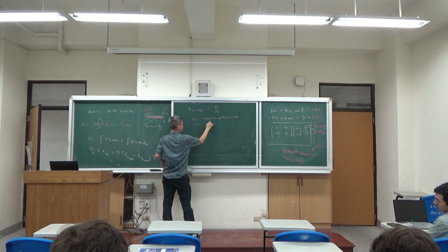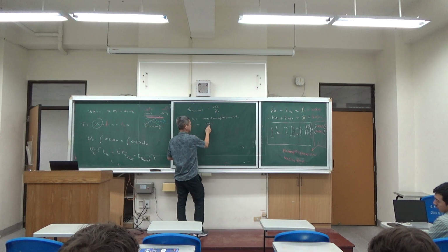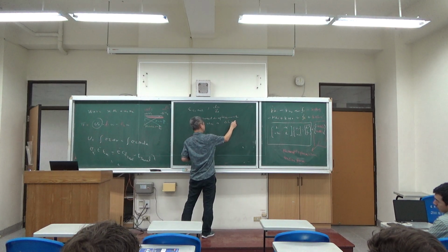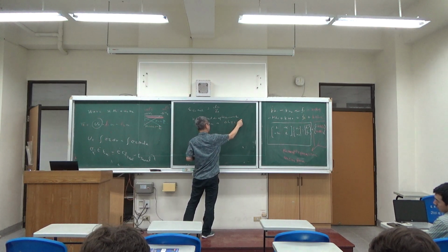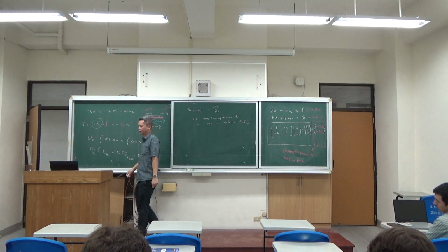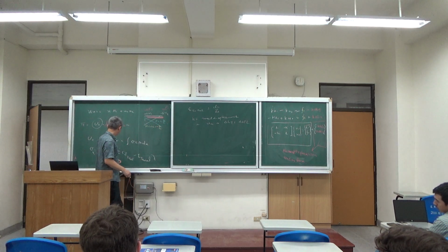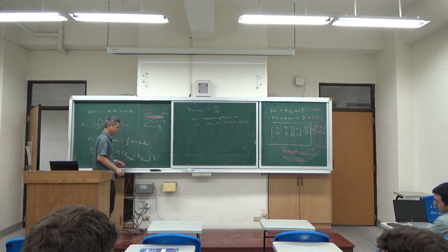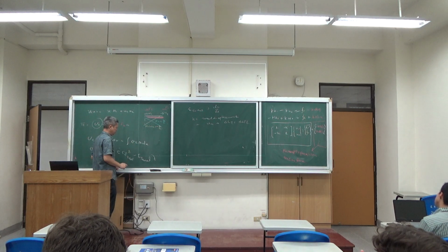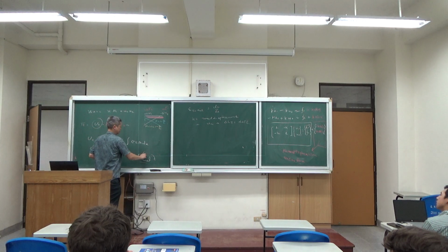It's due to the expansion caused by the cooling, and alpha delta T that is caused by the thermal expansion. So you have to do the correction here. For simplification, I write this epsilon to be the total strain, and this one to be the thermal strain.